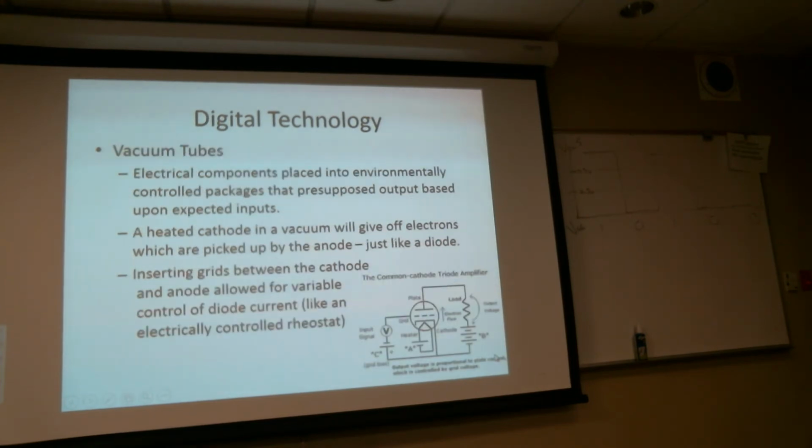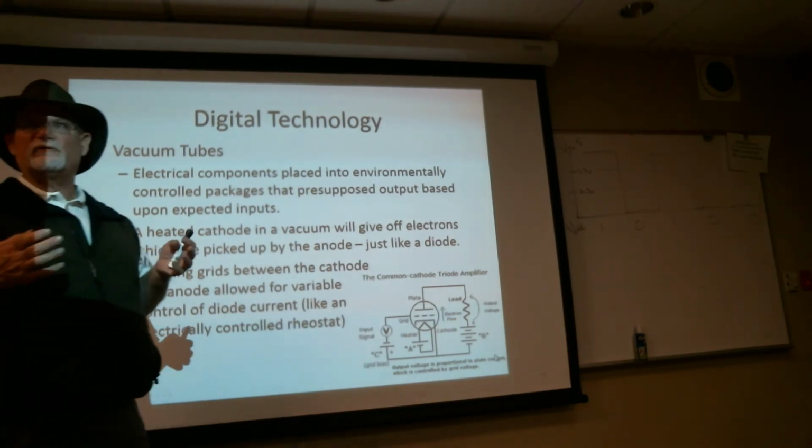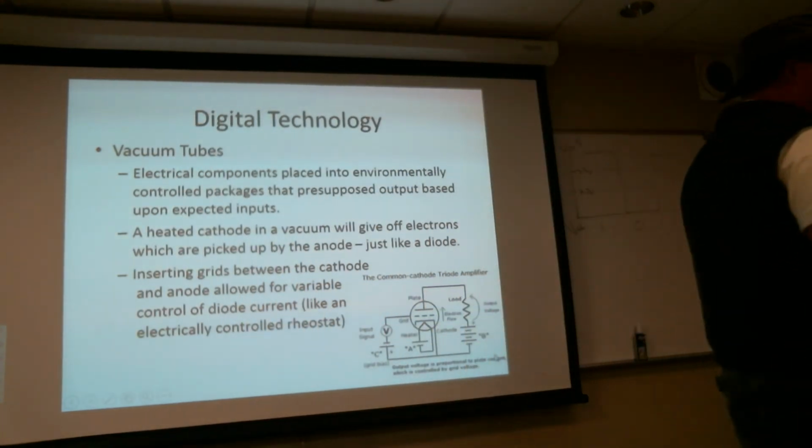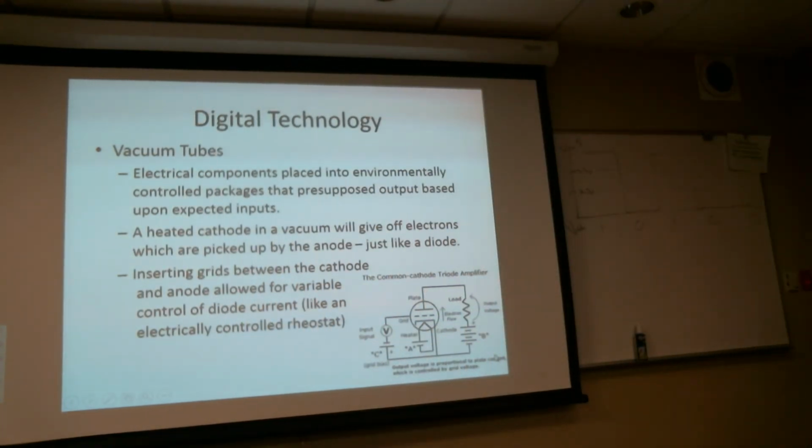So the vacuum tubes. We use the term vacuum. Oftentimes they were not actually in a vacuum. They filled the little chamber up with an inert gas, which did a pretty good job, and they were probably at a much lower pressure. But putting a little bit of gas in there means that the pressure differential across that glass is a lot less, so it doesn't have to structurally be so darn strong. Okay, and as long as it's an inert gas, it won't get involved in any of the electrical reaction, or at least a very limited amount. So other times they really were vacuum.